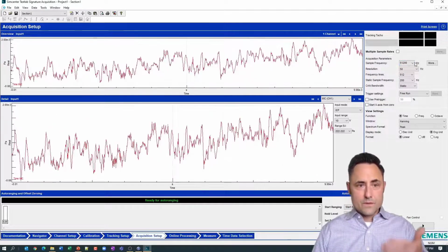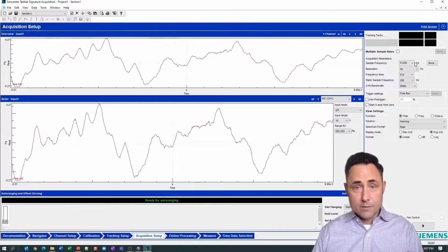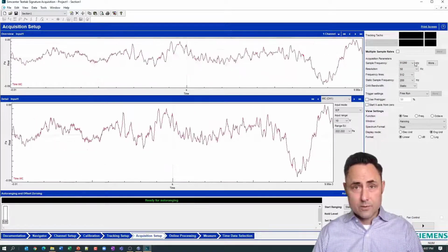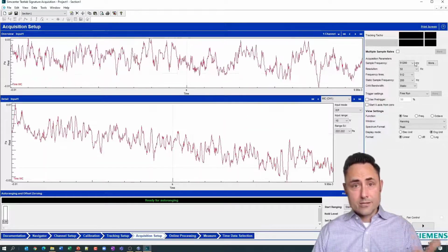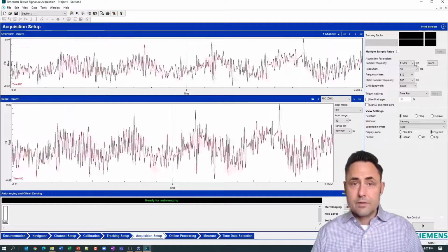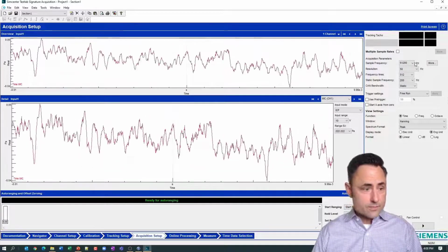Okay, so what this is saying is I've now turned on one mic. It's ICP, 45 millivolts per Pascal. I said take data when I tell you to start, and go for basically forever until I stop you, and sample at 51.2 kilohertz.